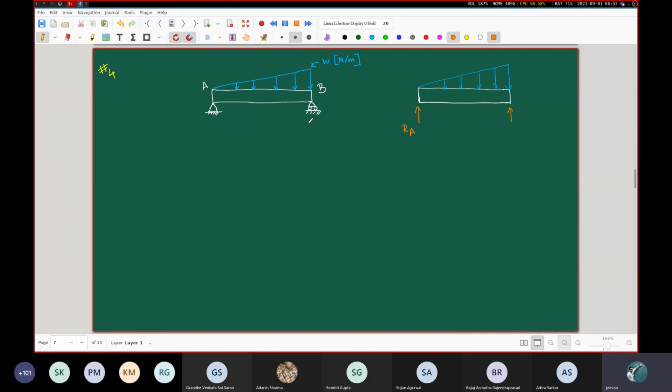Please note that on the right hand side, you have a roller joint. It's a pinned end, but a roller kind of thing. So here, there is absolutely no chance of any horizontal force appearing, because the presence of this roller indicates that there is no resistance to the horizontal displacement of this beam. Since there is no resistance, there is no reaction force in the horizontal direction. Which is why you have, theoretically speaking, two unknown reaction forces here, RA and HA, and one reaction force here.